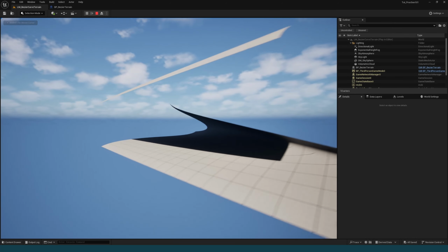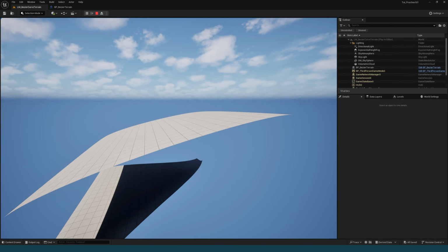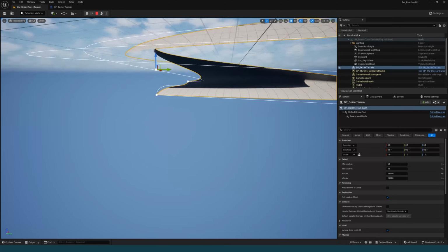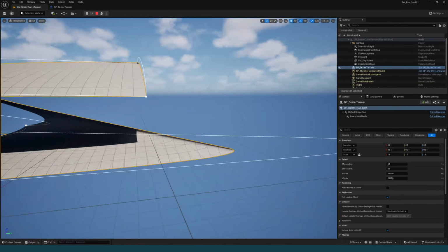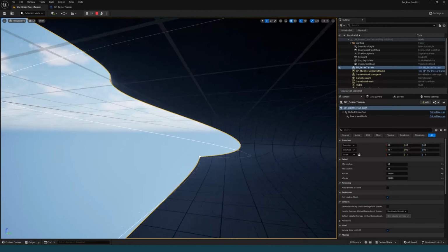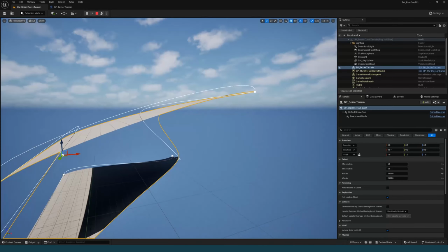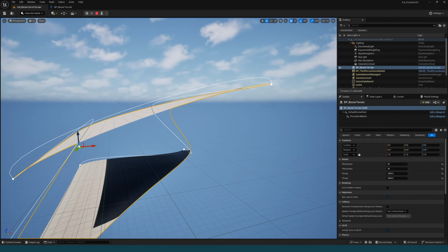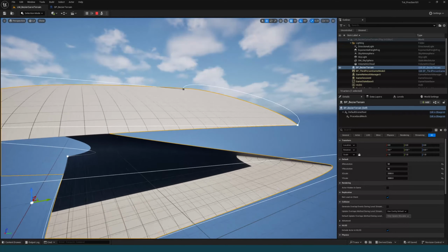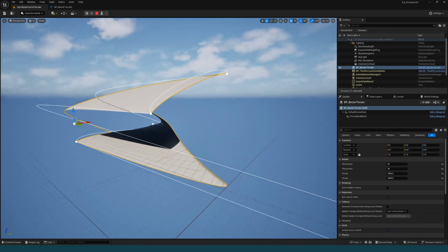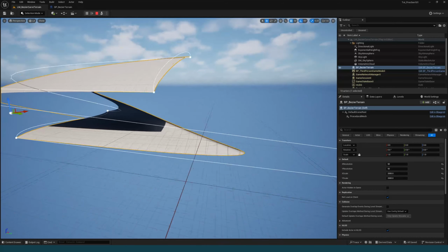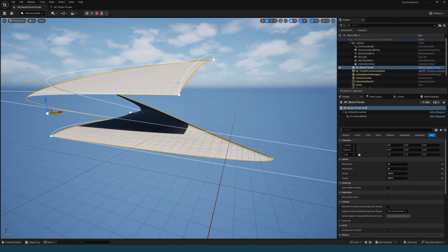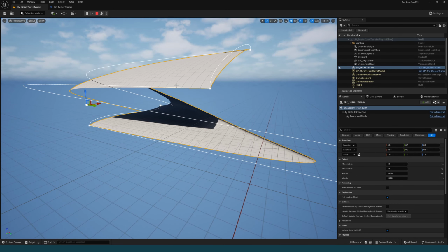So we're actually getting some very strange terrain since with our large tangent, we're actually looping the mesh over itself. So you will want to have some rules on how exactly these tangents can scale based on the size of your mesh. But you could also, if you wanted to put a double-sided mesh on this and just use this as one single piece of terrain, you could do that too. It depends on what your final use case will be. So let's go ahead and put a double-sided mesh on this just to see what it looks like.